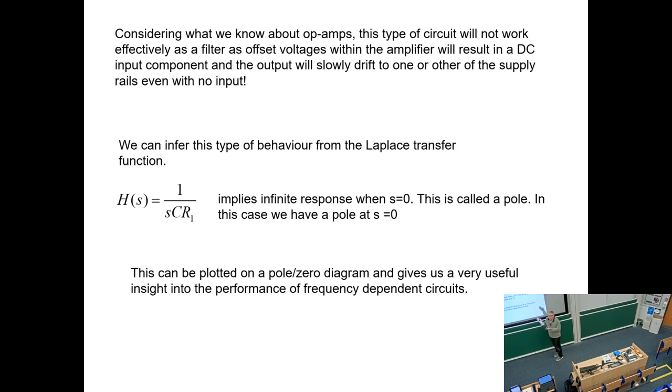Whatever you do, even with the best op-amp in the world, it's still going to drift eventually. It could take a long time, sometimes months. That's fooled a lot of people. They think their circuit is fine, it works for several months and then stops working, because they've forgotten about this drift. Very slow, but it gets there in the end. So just remember, this will catch you out.